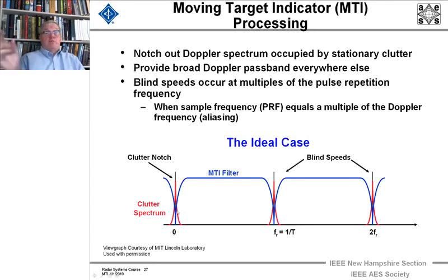And in the case of a rotating antenna, the amplitude modulation of the pulses as they go by a fixed object, like that imaginary sphere in space, is going to be amplitude modulated by the gain pattern of the antenna.